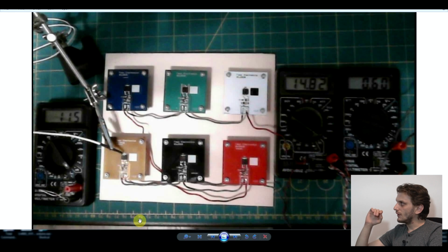And I did make one specific feature on the board that usually doesn't really make sense, and that is this white square on them. And basically this is a square just painted on them through silkscreen, but all the boards have the same paint on them, so the same emissivity. So it's a good way to compare how the rest of the solder mask behaves compared to this silkscreen. So let's look at each board and see what we got.